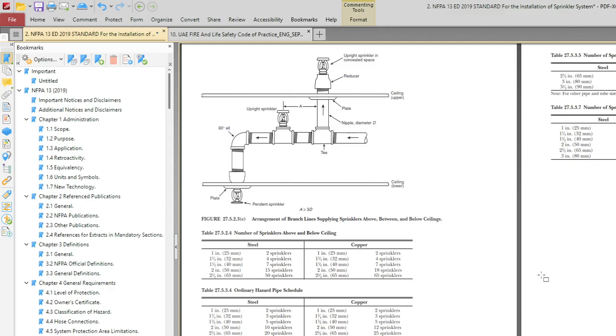But now we are talking about light hazard and ordinary hazard, not special applications. We have retail here, and above the false ceiling we are doing piping, and below we are just providing one zone control valve, and maybe the client will provide more later. We have already done the sprinkler network above the false ceiling, and we provide one more branch for the tenant.